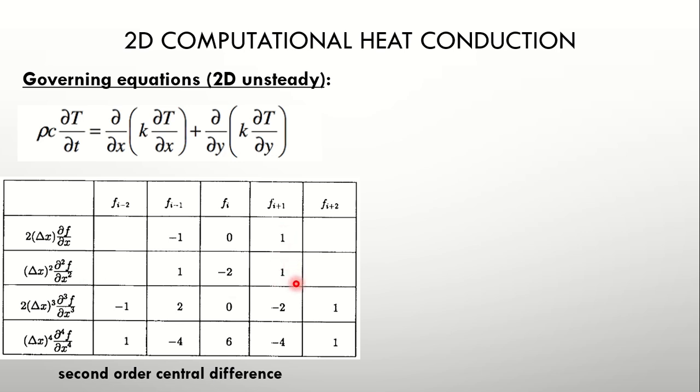Okay, so that is how you get ∂²T/∂x² as T of i plus 1 minus 2 into T of i plus T of i minus 1 divided by delta x squared. Similarly for ∂²T/∂y². Okay, so that would complete ∂²T/∂x² and ∂²T/∂y². Now what else is remaining is ∂T/∂t. Now you could also have done it using a central difference.